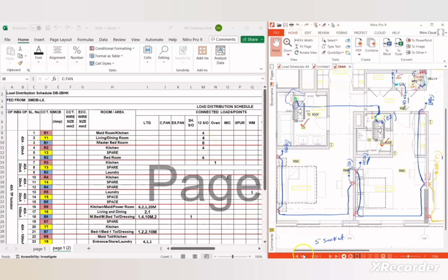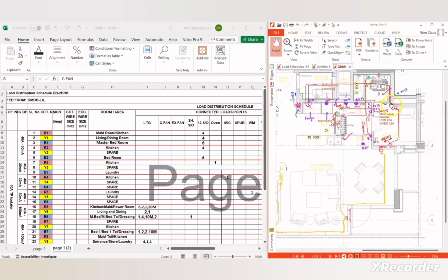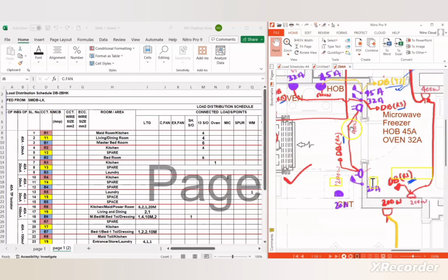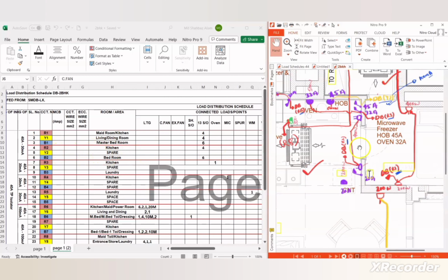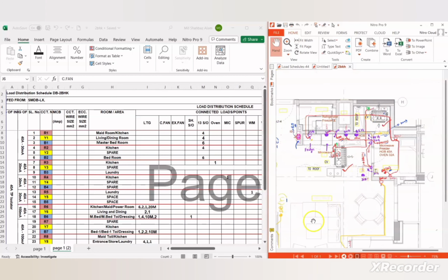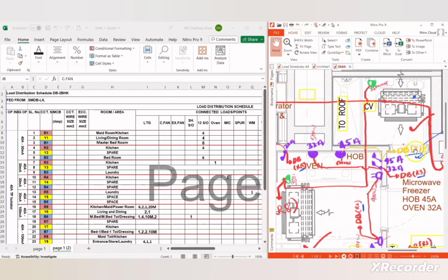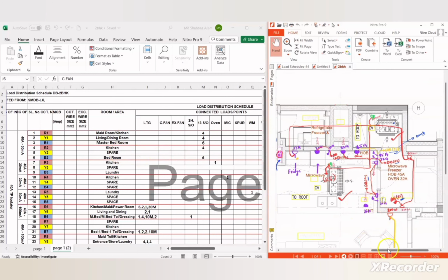Now again go to R2 circuit. Here you see that there is R2 circuit for a kitchen, general purpose socket. So R2 is kitchen, and total number of socket is 4. 2 socket, which is twin socket, so it will be considered as a 4 single socket. Okay. Y2 we haven't given to any of the circuits, because after Y1 we came directly to Y7 here. I hope it is clear to you, which I have given to Hob. So Y2 is spare.